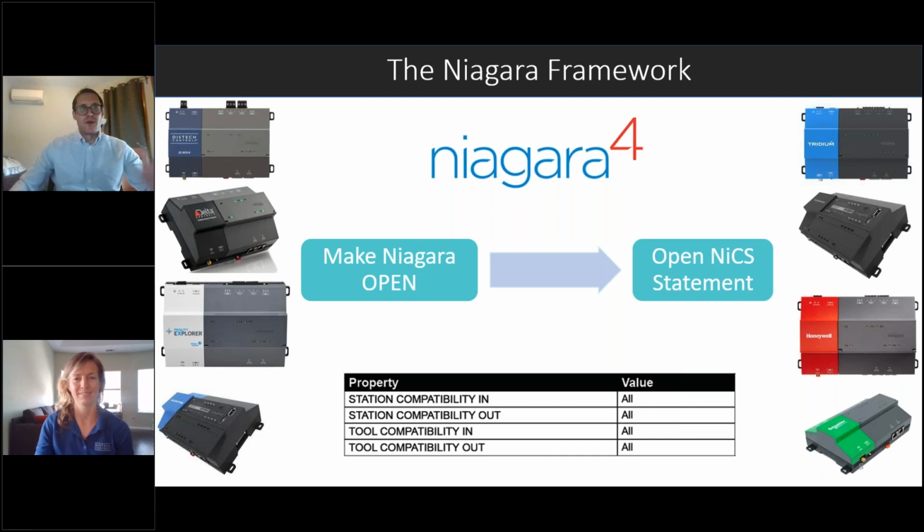So it's easy for one manufacturer to come in, look underneath, so to speak, underneath the hood of the controls engine and know what's going on pretty quickly if it's using Niagara 4, because it's not specific to any one manufacturer. It is important to make sure that it's open whenever you are using Niagara. Niagara does have ways to lock out the controller and software and tools available with it to a specific vendor. So you do need to be aware of that.